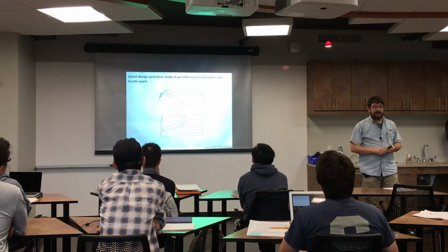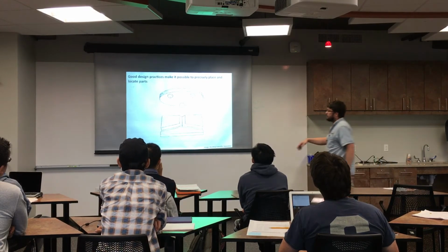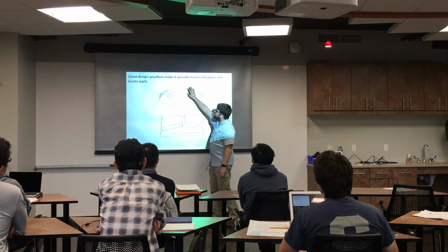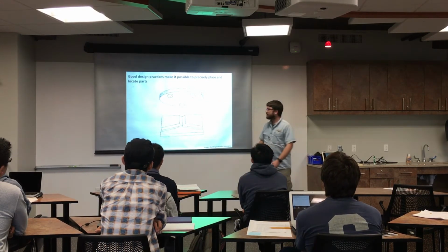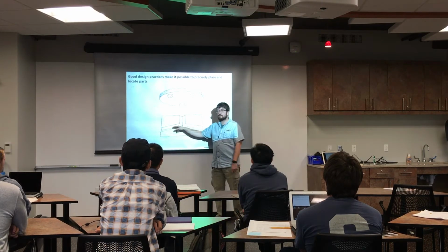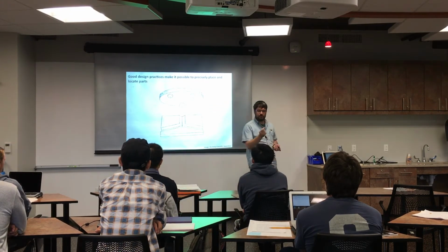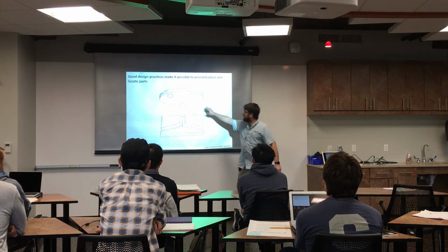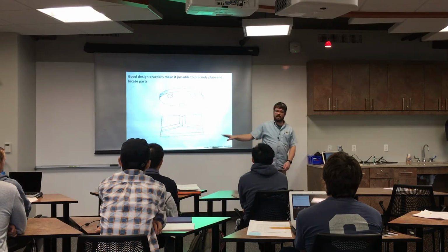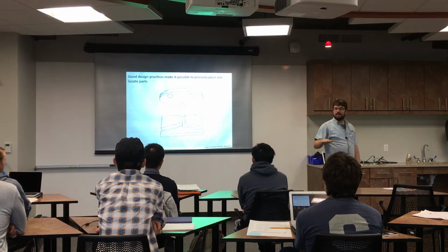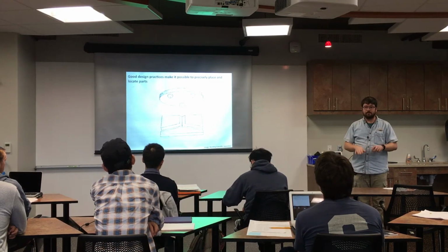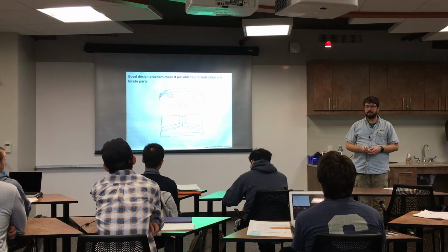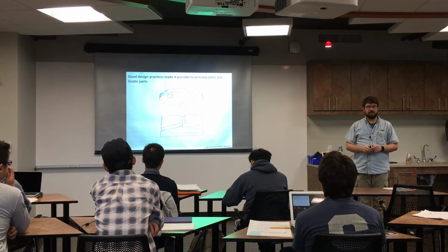You can combine multiple dimensions of this. So let's say we had some kind of sample holder up here, and we needed it to be precisely positioned in the same way every time. We could have a plate done with V-grooves or with U-grooves and those bars. And in this case, every time you set the plate down on here, it's going to be in the same spot. It's constrained in translation and rotation, right? So there's no degrees of freedom once this plate is down. So, make sense?